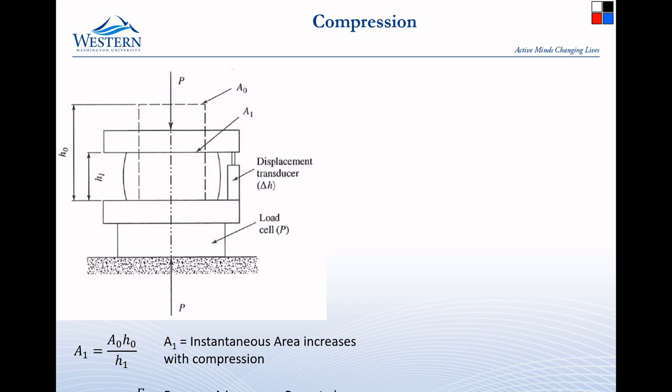Compressive strength. Compressive strength is bizarre. It is hard to find information on the compressive strength of most materials. And that is because most materials don't fail in compression. So they may have a compressive elastic response.